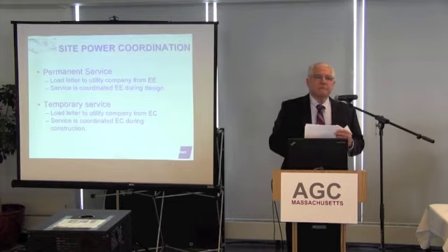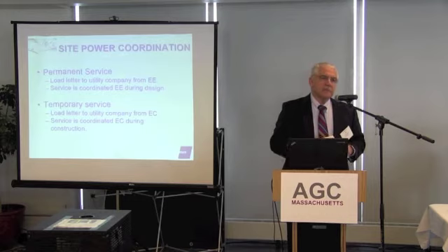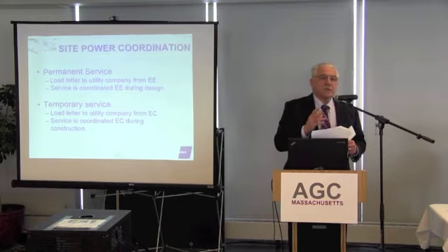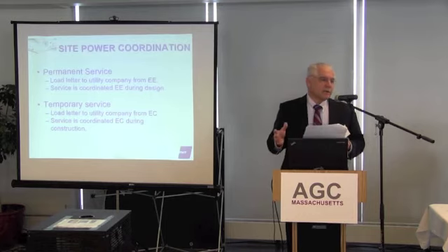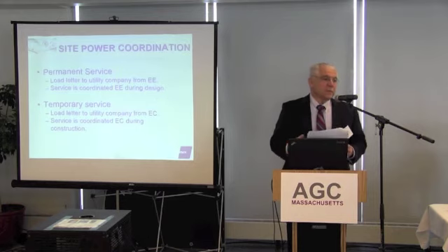They would expect you to standpipe that pole with your conduit, 4-inch conduit plus the spare, and that primary service would be run by the electrical contractor, the conduits, and go to the primary side of a transformer. The transformer pad is the responsibility of the civil contractor or the general contractor. So that's usually put in place for the electrical contractor.